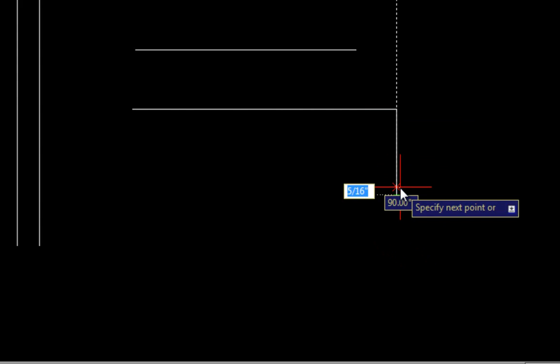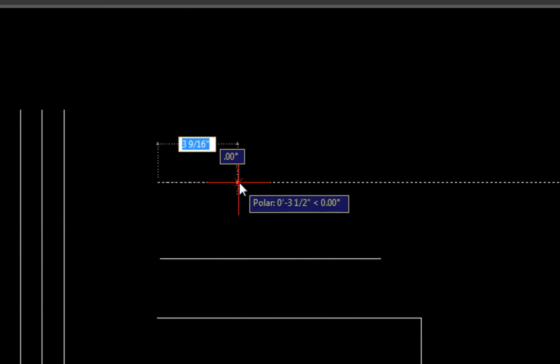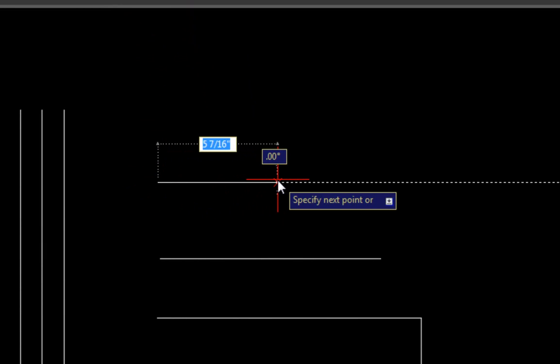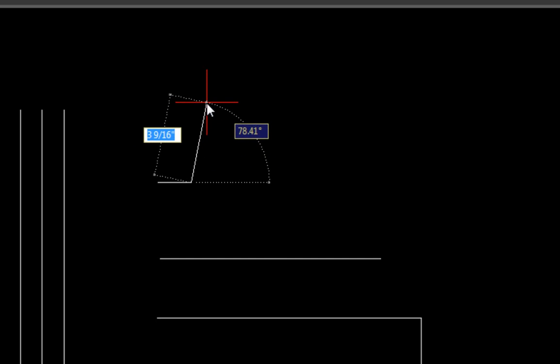Now another thing that's a little challenging is when you have fractions. So if I am pulling my line and I want to make a measurement that's 1.5 inches, if I'm pretty decent at math, I could just type in 1.5, meaning 1.5 inches, and hit enter, and there my line's 1.5 inches.